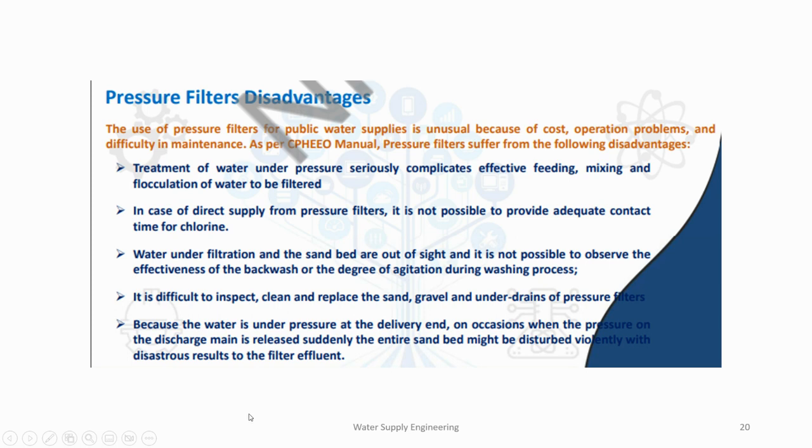And another major problem is, since the water is being treated under pressure and the water is under pressure throughout the pressure filter, when we are suddenly releasing it to the discharge mains, there are chances that the filter bed may be disturbed violently. So the filter effluent will also get disturbed due to this sand bed disruption.